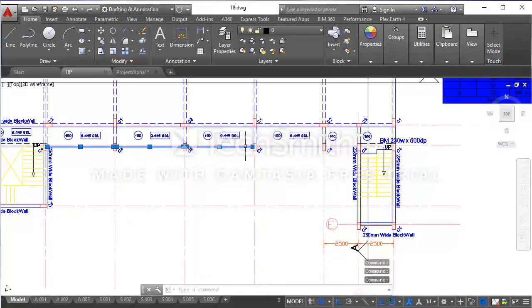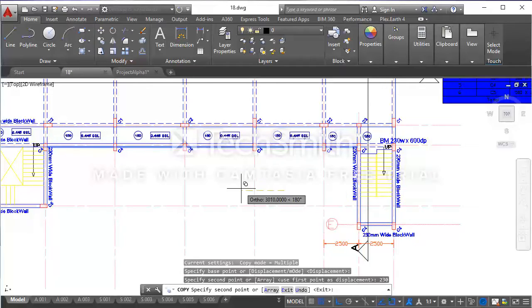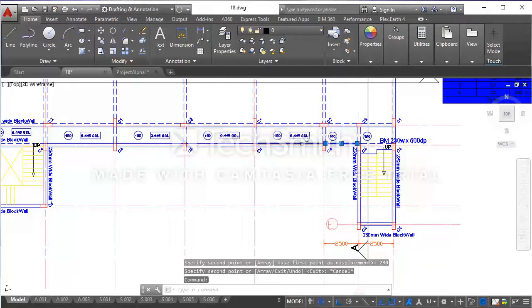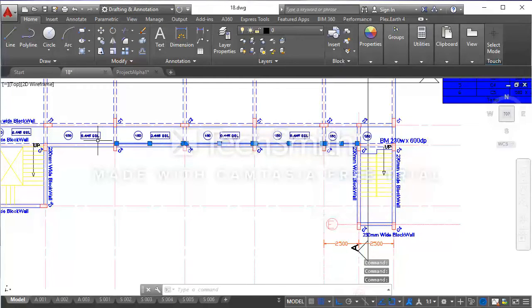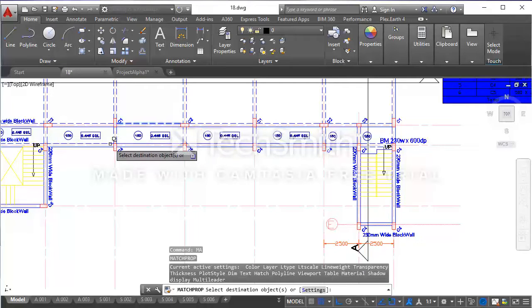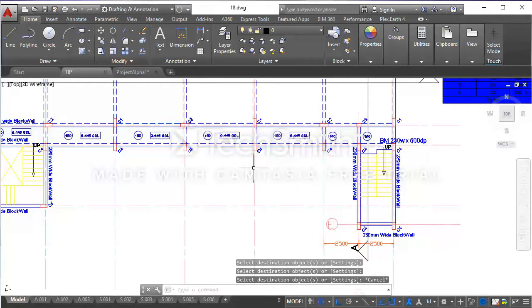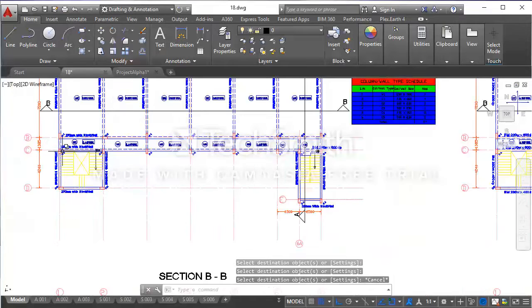this edge of the floor slab and I will copy it, duplicate it 230 mm upward to denote our 230 mm block wall. This inner line will be depicted in hidden line property because it will be hidden below the ground floor slab. So I'm going to select this hidden line type, match property on my screen and apply it to these lines. So we have a 230 mm wide wall along the line C.